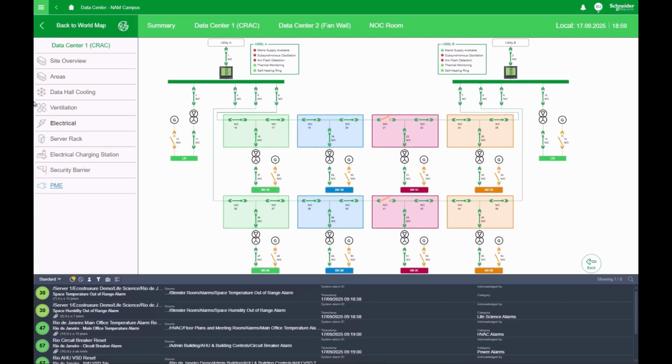We all know the data center market is rapidly growing. In addition to that, data centers are growing in size, they're becoming more complex, and with the advent of AI, we see inconsistent and sometimes unpredictable load profiles as well. All of this is leading towards more automated MV power systems. In addition, we do see IEC 61850 becoming more prevalent as a protocol as it's more future proof, it's faster to deploy, and we've also seen that it's easier to test at factory.